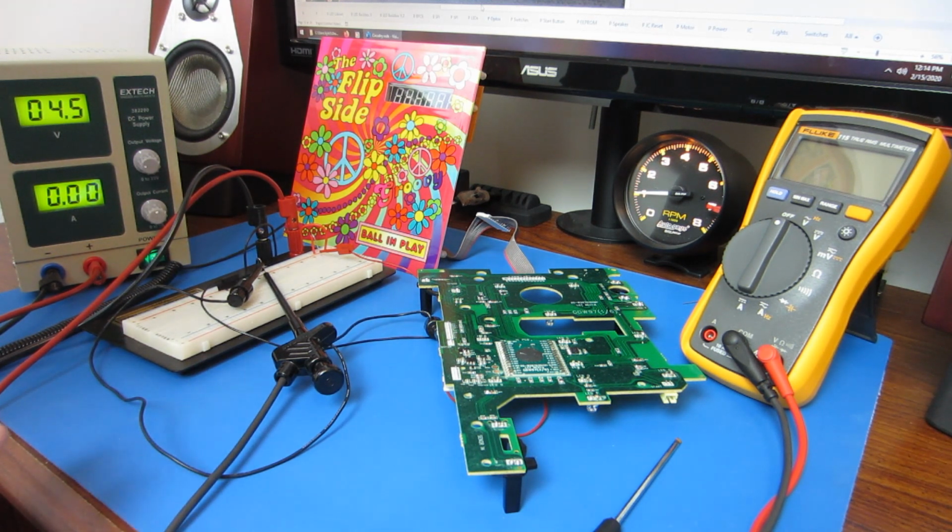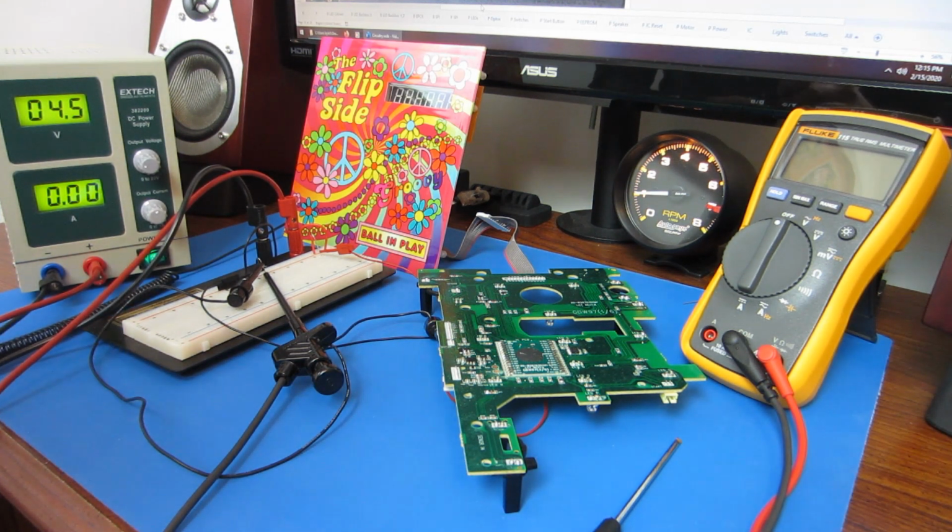I'm expecting it to be kind of in the middle. It'll be less than 3.5 and more than 0. And the multimeter is not fast enough to show the oscillation, so I'm hoping that this logic probe can show me that indeed there's some binary data going across that and it's oscillating very quickly. I'm going to get that hooked up. I'll be right back.